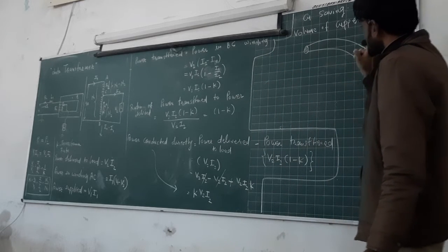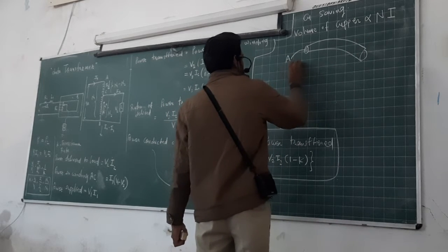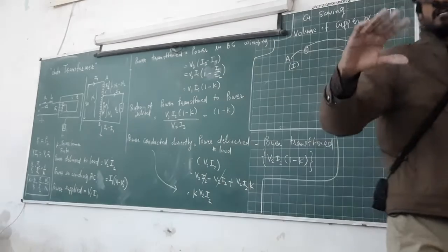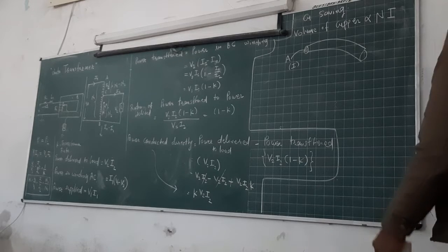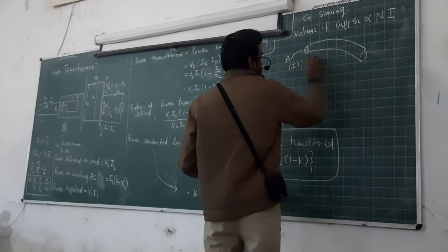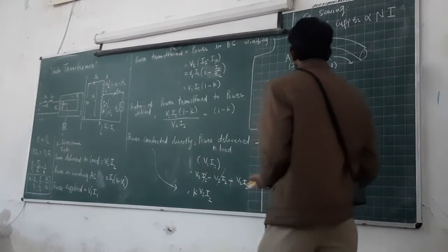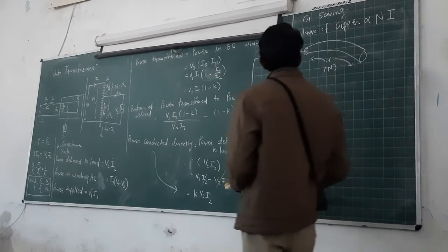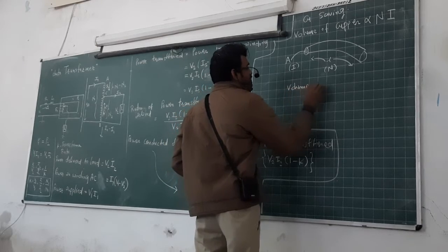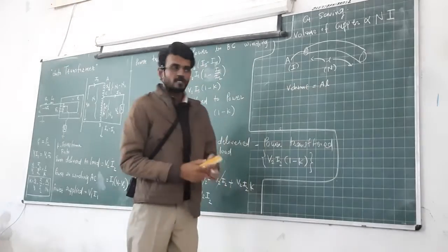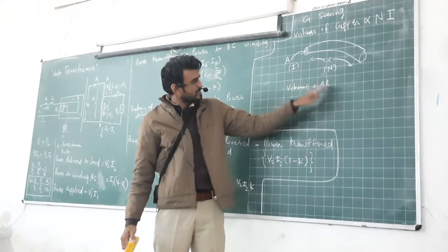Okay, so cross section area will give me direct information about current, because the higher the cross section area, the larger current it can carry. Okay, and length, or number of turns, gives me the idea about length. Okay, and volume is cross section area into length. Okay, area into length is the volume of the copper. So copper volume is cross section area into the length.